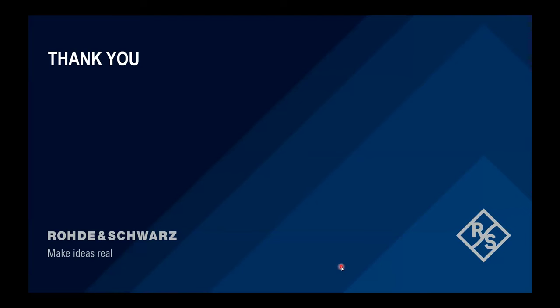Next one was, how many seconds is the appropriate transient time at startup? Basically, there is no real rule of thumb because this all depends on your power up behavior. If you'd like to switch on everything quite fast in your design, you'll need a high amount of current from your grid or your supply. If you think about a mains connection, this might not be such a huge issue, but if you think about a battery powered device, the battery will provide you a maximum current.